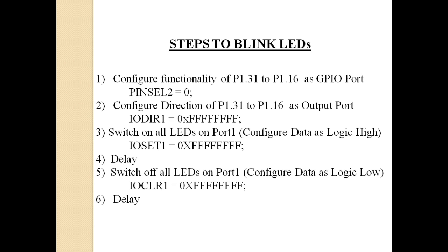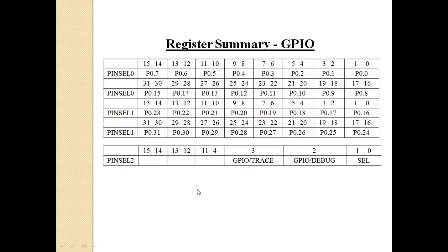right? So it will ensure that both the on and off states stay in my eyes for at least half a second. Then only I will be able to see the blinking effect. If you remove these 2 delays, I will see that the LED is always on. That on and off state I will not be able to distinguish. That is why you are adding the delay. Right? So next slide, this is known as a register summary.